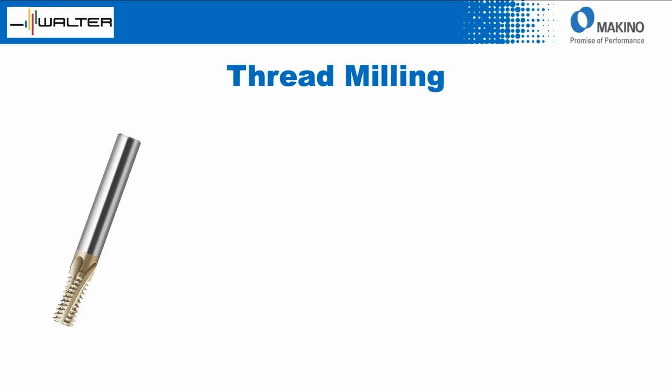All right, let's move on to the third of the processes we're going to talk about today, Brian, thread milling. Okay, what we see here is a conventional thread mill. This is what most people are familiar with, this full thread length design, and it's a very universal tool. In addition to that, some of the newest style thread mills that we'll be seeing is this multi-row design. This is going to be a real revolutionary change for thread milling, and we'll touch on that in just a couple seconds here.